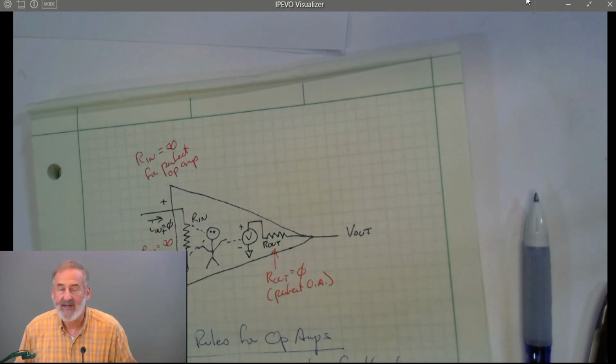So in the op amp, negative feedback means that the output of the op amp can control the negative input of the op amp. If the output goes higher, the negative input goes higher. And of course, if the negative input goes higher, it causes the output to go lower. Similarly, if the output goes lower, it causes the negative input to go lower, which means that the positive input is at a higher voltage, the output goes higher. So in general, you can tell if there's negative feedback if you see some sort of connection between the output of the op amp and the negative input.